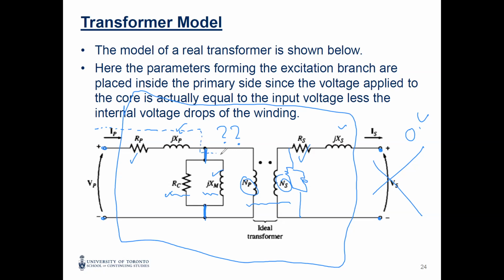Because of the flux in between, even if this one is open and there is no circuit, you will find that there is a voltage here. If you put a voltmeter, you'll find a voltage because of the flux flowing in the mutual or magnetization. Because of the flux, there is a current flow, eddy current, and hysteresis losses. So you will find heat in the core.